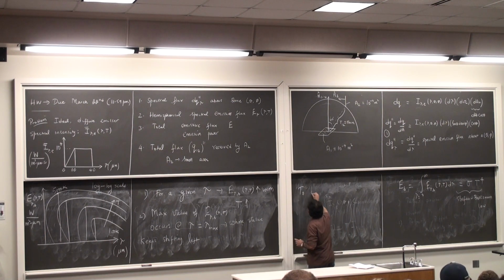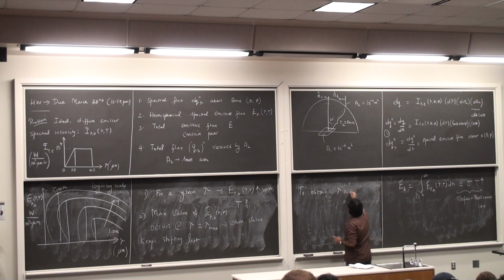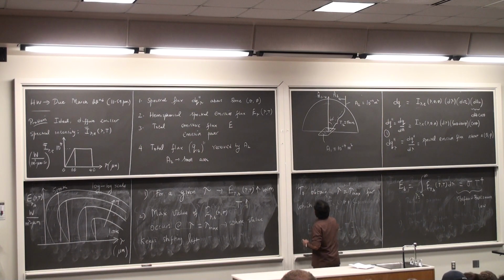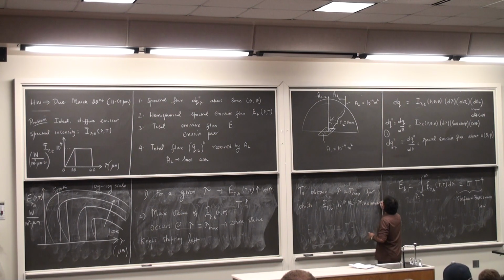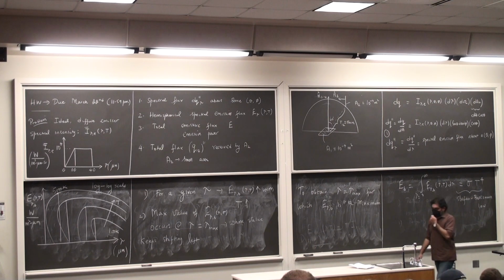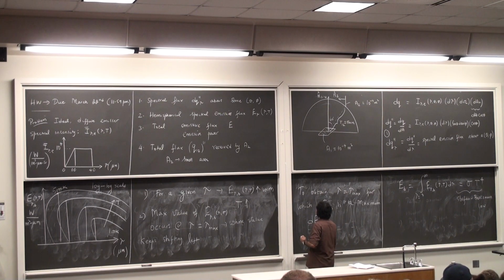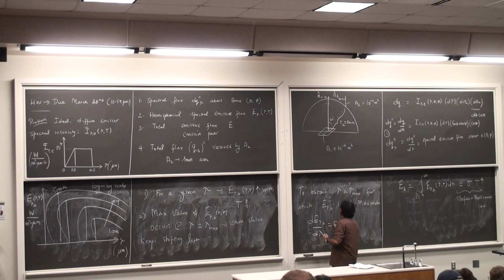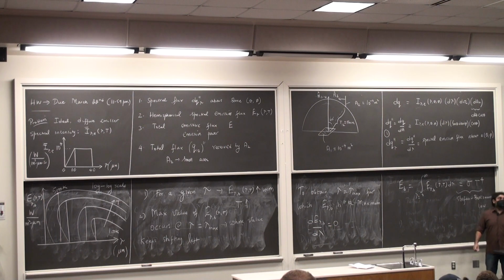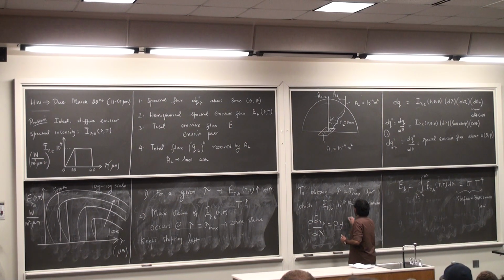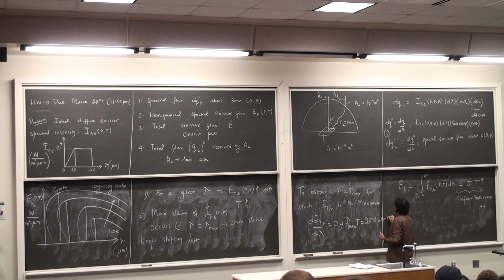To obtain lambda equal to lambda max, for which E lambda comma B is a maximum, you differentiate E lambda comma B with respect to lambda and set it equal to 0, and if you do the differentiation, you end up with the following equation: lambda max times T is 2898 micrometer Kelvin, and this is called Wien's law of displacement.